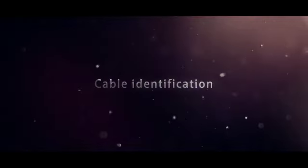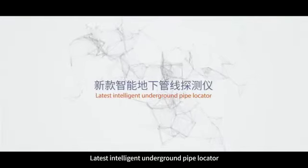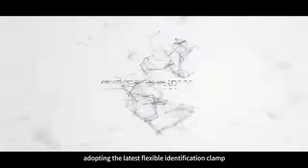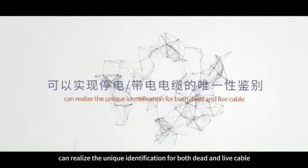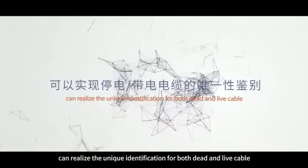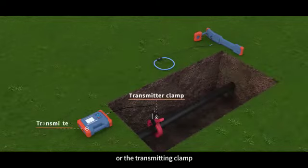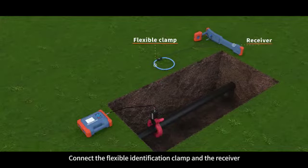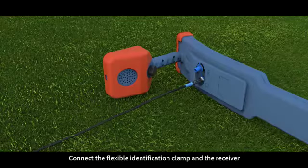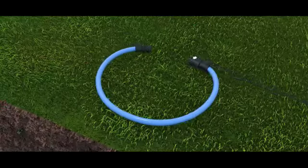Cable identification. The latest intelligent underground pipe locator, adopting the latest flexible identification clamp, can realize unique identification for both dead and live cable. The transmitter, through the direct connection or the transmitting clamp, applies a special composite frequency signal to the cable. Connect the flexible identification clamp and the receiver. The device will automatically change to the identification mode.